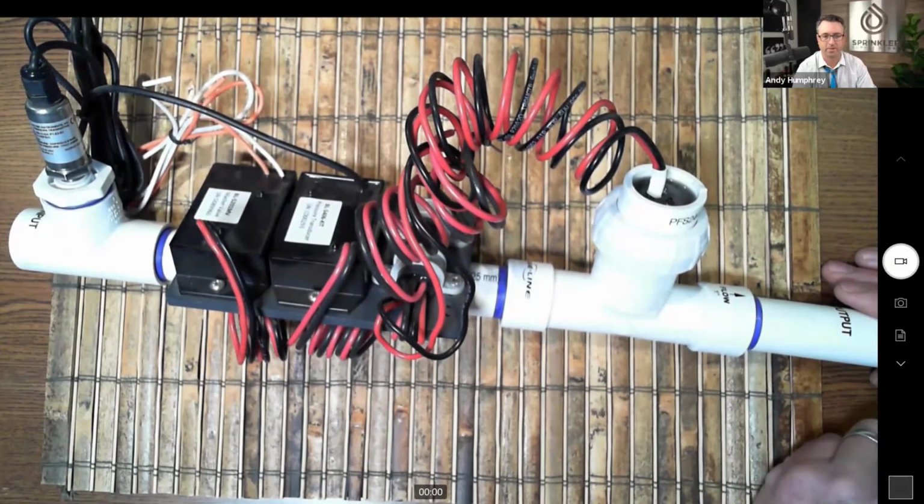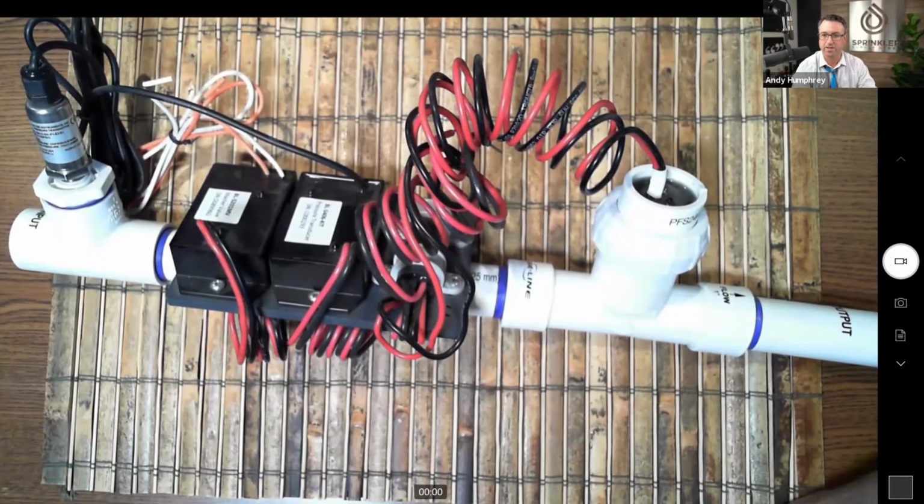Yep. And then keep in mind too, I think we'll get into this on maybe the next product you bring out. These devices are 2-wire devices, right? However, if you have a conventional system and you don't have a 2-wire in the field, you're going to connect it to the 2-wire port of the controller. Correct. And so what we're talking about here applies to conventional wire and 2-wire. It's just that if it's conventional, you have to run the wire directly into the controller.